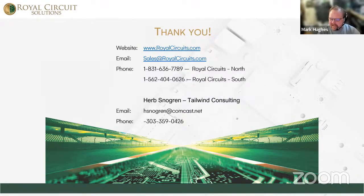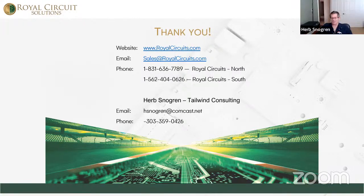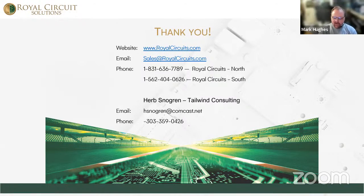Amba asks, are EDA tools available for Ultra-HDI? I think I can answer that one. They are. There's really not much difference between an HDI design and an Ultra HDI design, except the feature sizes. So I believe they're there. Yeah, I was going to say the same thing. Pretty much any EDA tool, even the free ones, should be able to do this. It really comes down to having different design rules more than anything else.